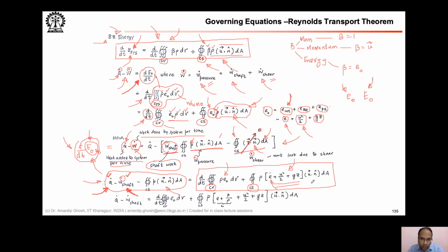an idea. So if you know the temperature and you know the CV, you can find what is your internal energy, or specific internal energy. U square by 2, U comes from the macroscopic velocity of the chunk, okay, not the molecular translation velocity. All that molecular description is taken into account in that first small u. U square by 2 gives you the macroscopic velocity of that infinitesimal chunk.